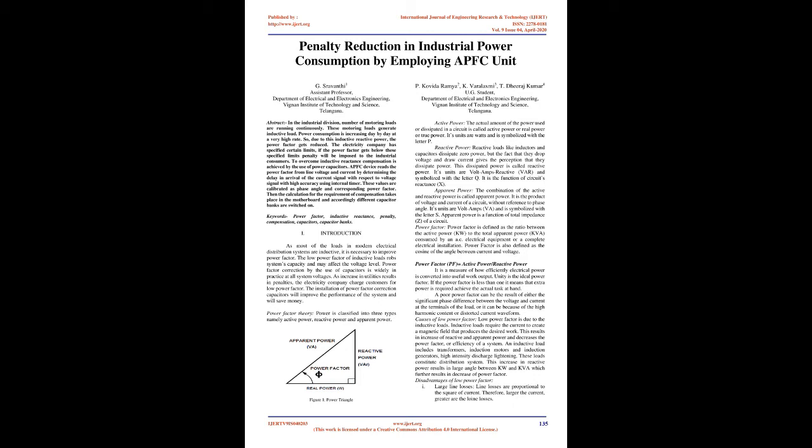So, due to this inductive reactive power, the power factor gets reduced. The electricity company has specified certain limits. If the power factor gets below these specified limits, a penalty will be imposed on the industrial consumers. To overcome inductive reactance, compensation is achieved by the use of power capacitors.